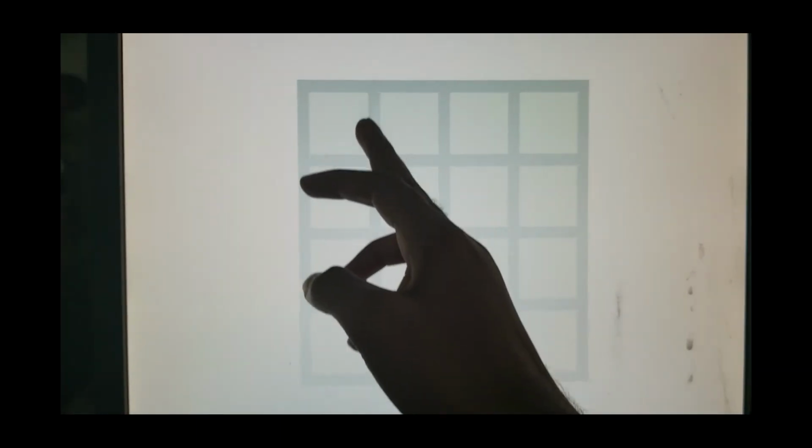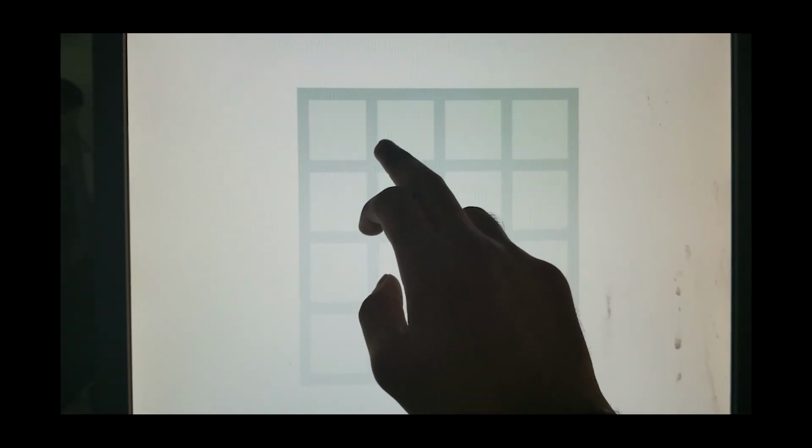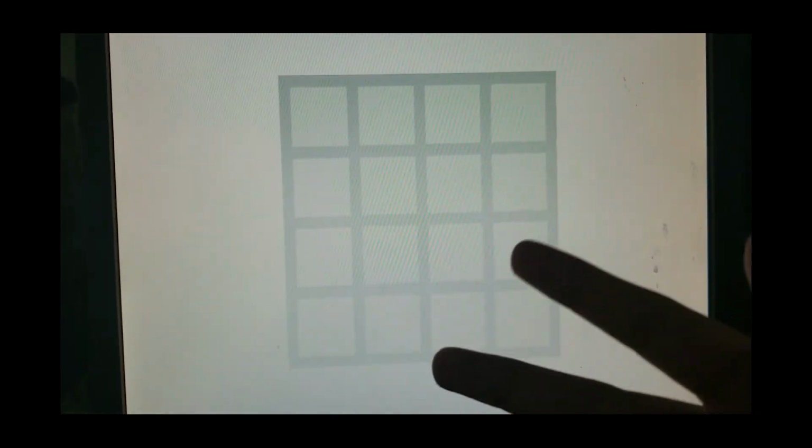And to get these crisscrosses, we used one-hot encoding. Once our pixel reader gets to this point, it goes high, and it tells us that because this is above the board, to put this color. But once it goes low, it goes back to the board color, and that's how you get this pattern. Same thing going down. We did it cell-wise in each row, and then row-wise. The row will go high whenever one of these is high, and then to display it, you just put in your X, Y, color, and position.